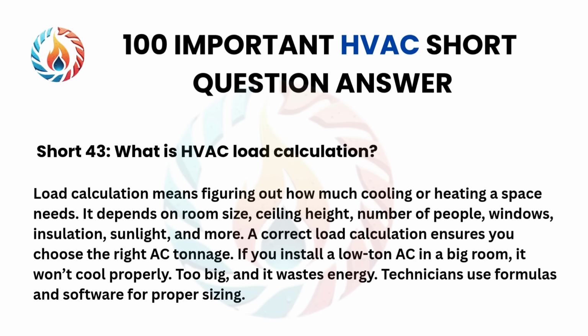Short 43. What is HVAC load calculation? Load calculation means figuring out how much cooling or heating a space needs. It depends on room size, ceiling height, number of people, windows, insulation, sunlight, and more. A correct load calculation ensures you choose the right AC tonnage. If you install a low-ton AC in a big room, it won't cool properly. Too big, and it wastes energy. Technicians use formulas and software for proper sizing.